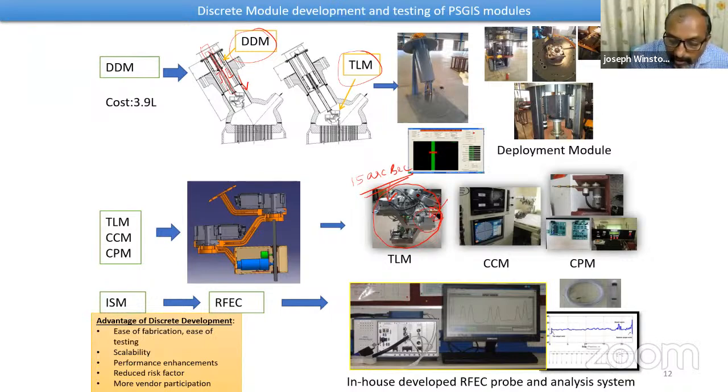Also, in this entire system, there are 2 tiny servo drives here, 1 servo drive here and 1 servo drive here. All these servo drives are interlinked by the CAN communication protocol, and the integrated program is done on the control panel. The control panel has a layout, which you can see here, similar to the tube sheet having the holes. The operator touches the particular tube and says execute, then the arm unfolds and goes to orient to that particular tube.